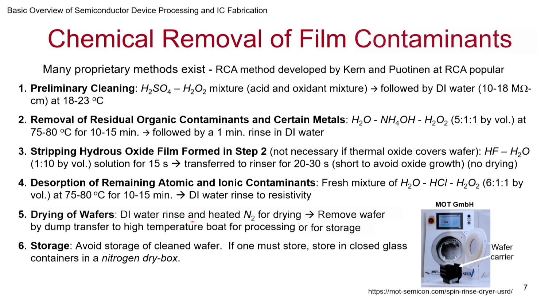Then usually after cleaning, you don't store it. You try to make sure the process keeps going, but sometimes you may have to wait because the equipment might not be free. In that case, you send it to storage, and you have to be careful how you store it. You put it in a glass box, glass container, and then you have a nitrogen dry box. So there is no humidity, and pure nitrogen is flowing, and you ensure that there is no reaction. As far as possible, oxygen and other things should be avoided. So this is the standard process that's often used in the industry and in many labs as well.